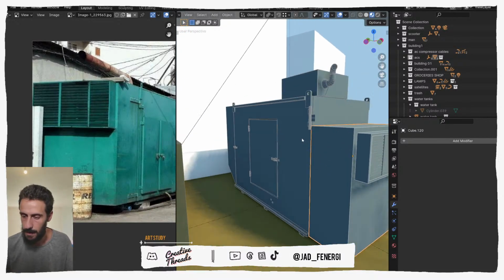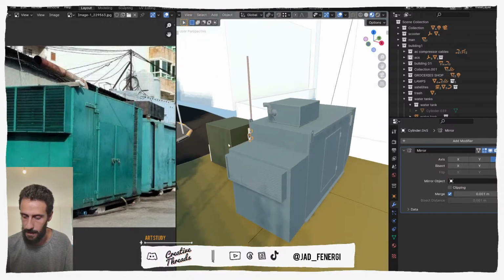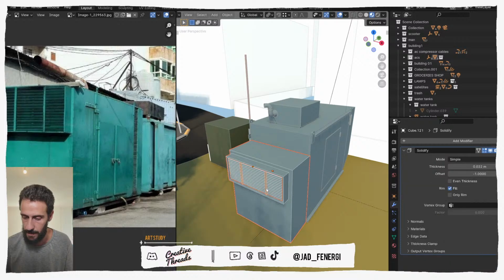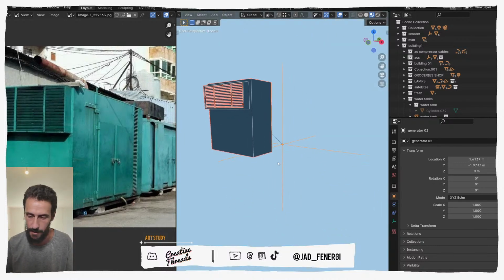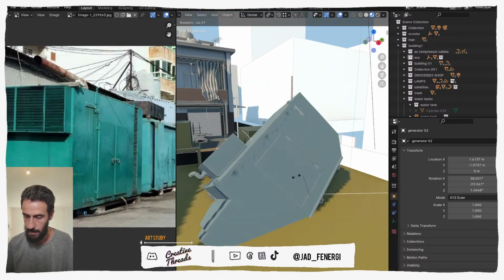All right, now we want to adjust the hinges and this whole side because it looks a bit different. What we want to do is assign these to the same empty that we have for all of these. So let's just pick also the empty here. Press the / just to make sure that we don't have anything else selected. Make sure that the empty is the last thing selected. Press Ctrl P and key transform. So now they are parented to the whole thing.